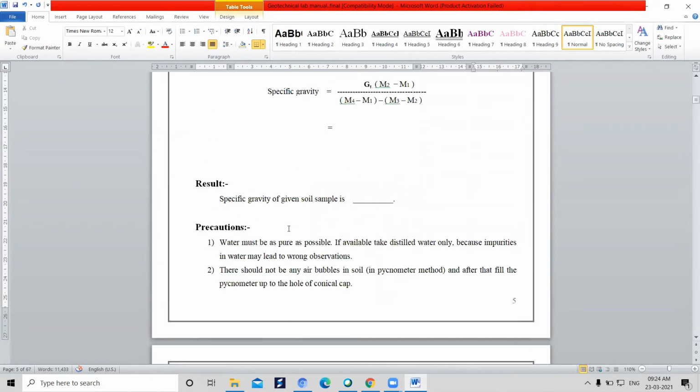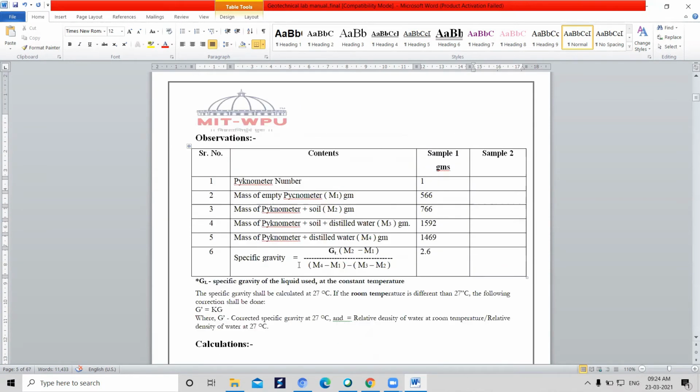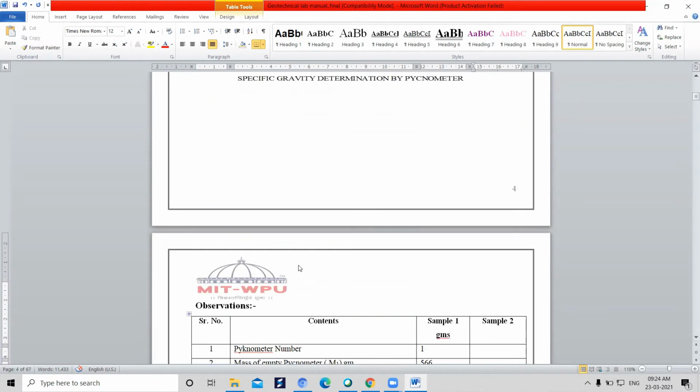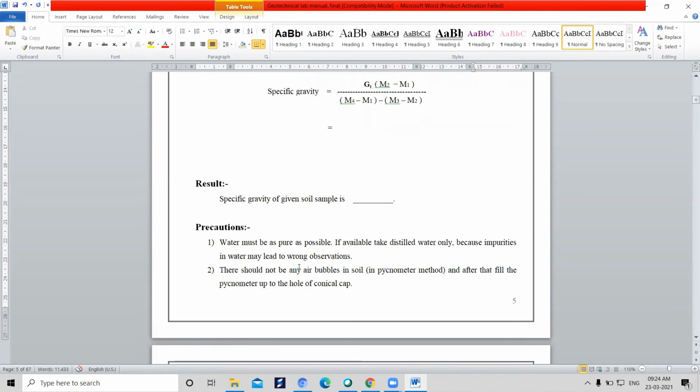Chalo. So, what is the use of the specific gravity? We find out here the specific gravity of the soil. Then what is the use of it? The specific gravity will be used later on to evaluate and for design purposes. For what design purpose? To find out the voids ratio, to find out the saturated densities, okay, to find out the bulk density too. We will be using this. Here are a number of parameters where by this basic specific gravity we can find out the various parameters further.